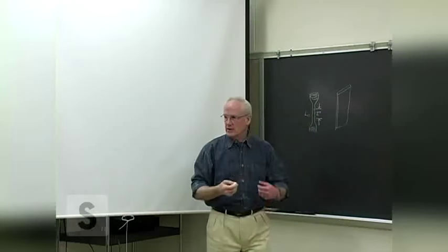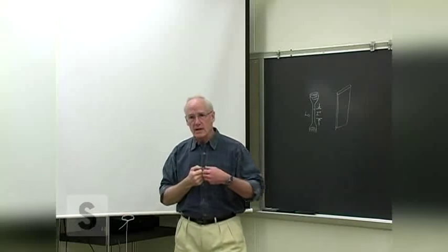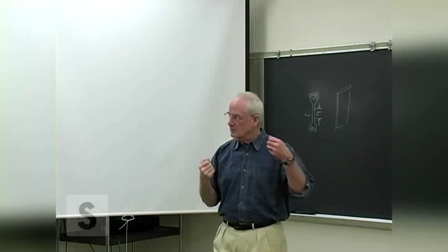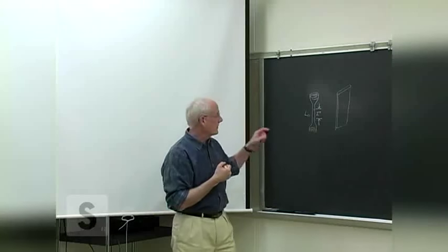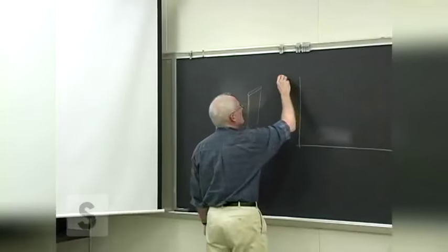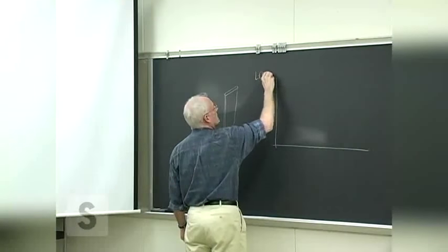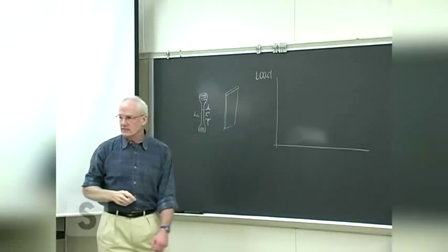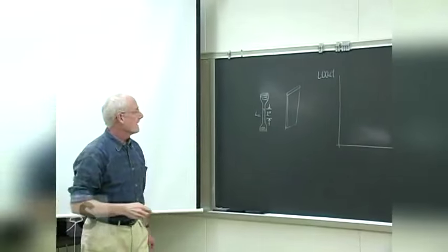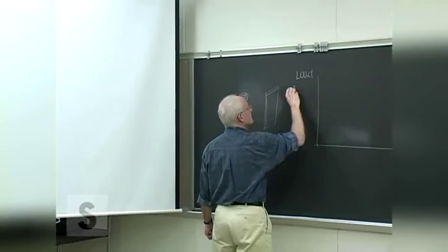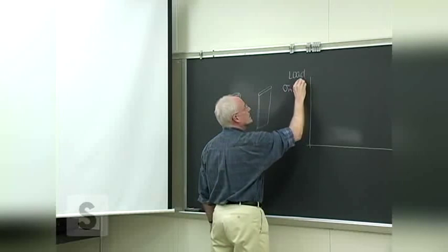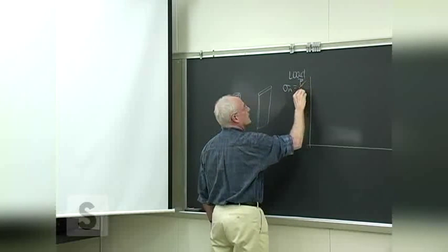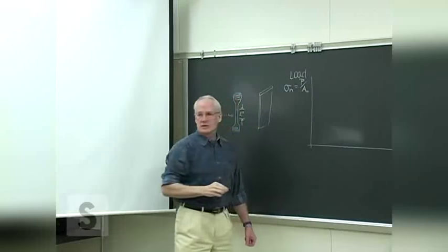And then it's put in the jaws and can either be pulled in tension or pushed in compression, very often both, not both with the same piece. A load, or some representation of the load on the y-axis, typically in terms of the normal stress, which is the applied load over the original area.